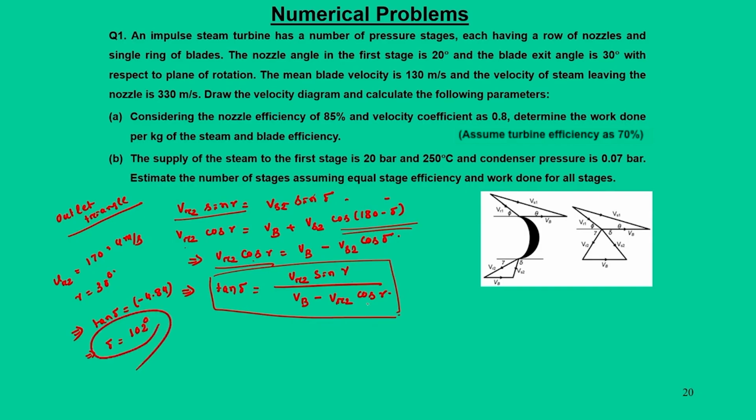And here you will see that this term will be a negative term because the denominator term will be a negative term, and that means this number would be 85.2 divided by minus 17.6. So, the ratio gives tan delta as minus 4.84. So, this gives delta as 102 degree, that means this delta is greater than 90 degree.